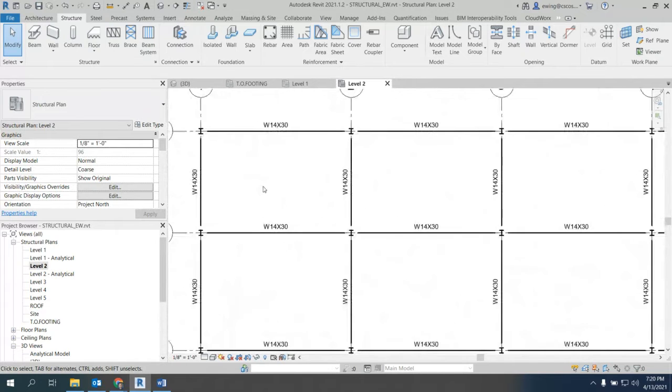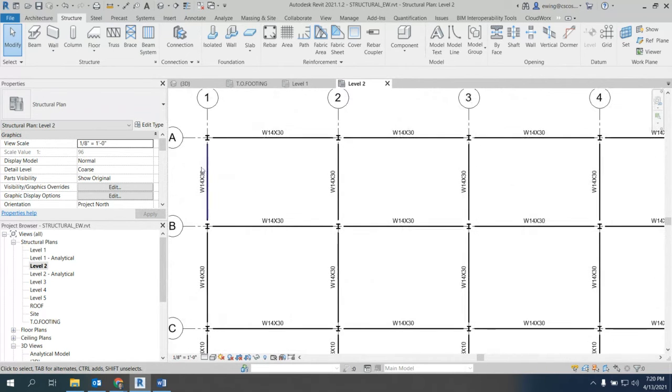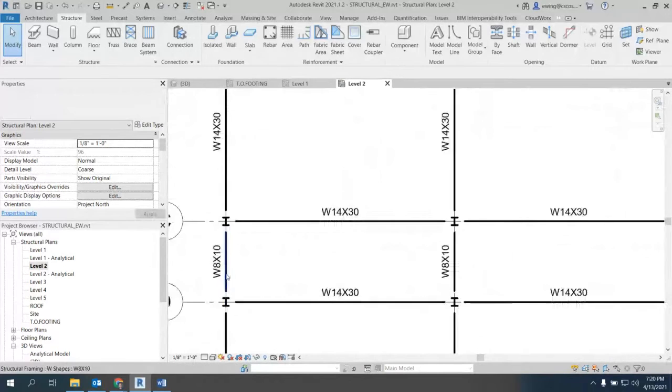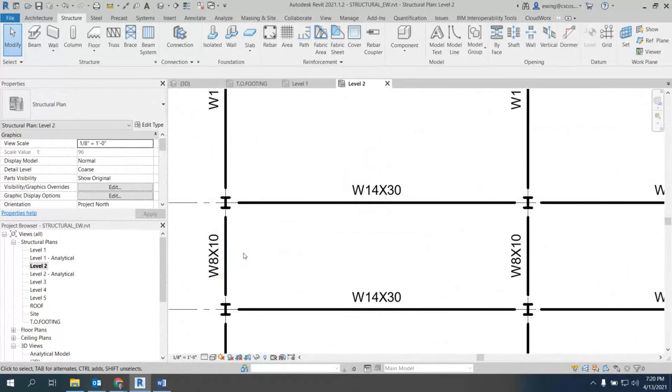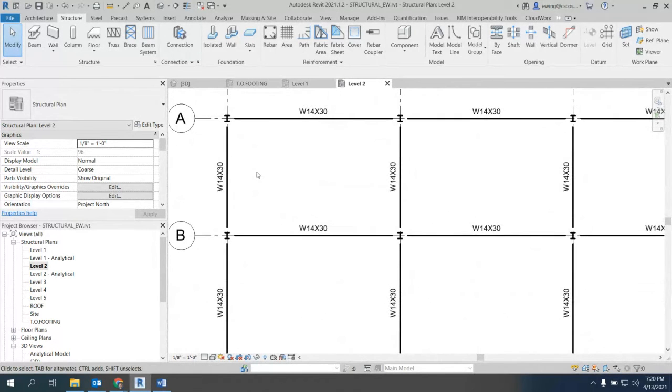Now, like I said, that's a 25-foot by 16-foot giant gap. We can't span that, right? So we need filler beams to go in here. They can be smaller, not W8s. These are small. But I think W12s work perfectly in here.